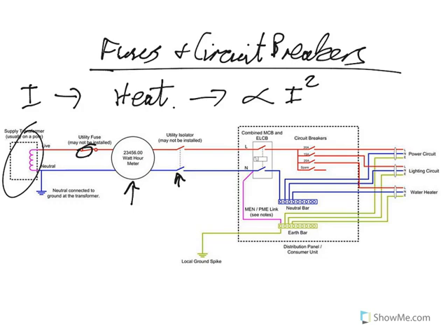Alright, then the first thing that comes into the meter box is this thing here. And this is our earth leakage protection, and we'll get on to earth leakage protection a little bit later. So I've actually gone to the earth wire and the fuses first in the notes. But essentially, you've got current going in and current going out, and the earth leakage protection monitors them to make sure they're the same. If they're not, it switches off your power.